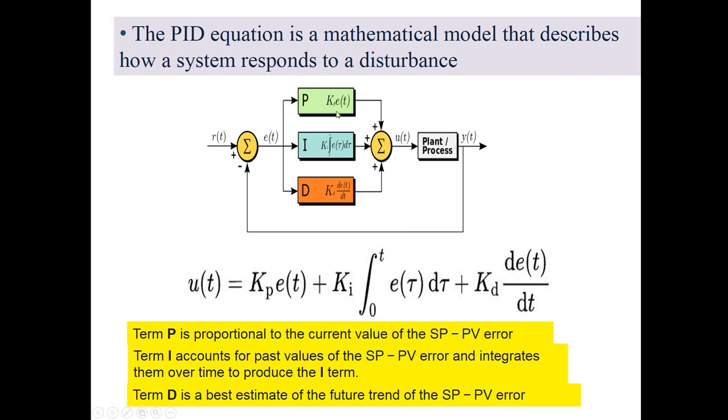The PID algorithm says you take a multiplication of the error over time, and also the integration, the addition of all the errors, and also the difference of errors, and then add them together. The final output you get is fed to power the heater, and from the heater the temperature can again be fed back to have a closed loop mechanism.